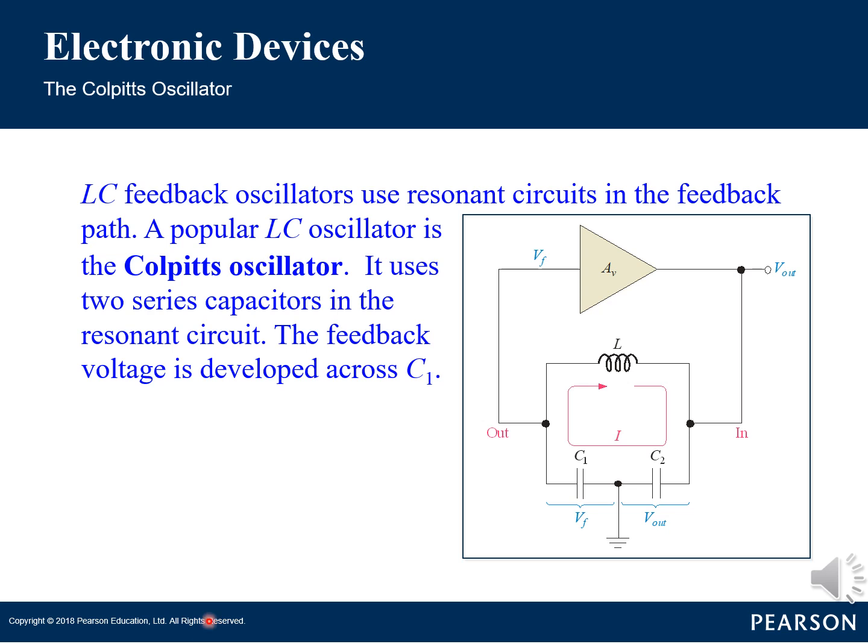Although the RC feedback oscillators, particularly the Wien bridge, are generally suitable for frequencies up to about 1 MHz, LC feedback elements are normally used in oscillators that require higher frequencies of oscillation. It works on the principle of positive feedback, where a portion of the output signal is fed back into the input, causing the circuit to oscillate and generate a continuous waveform.